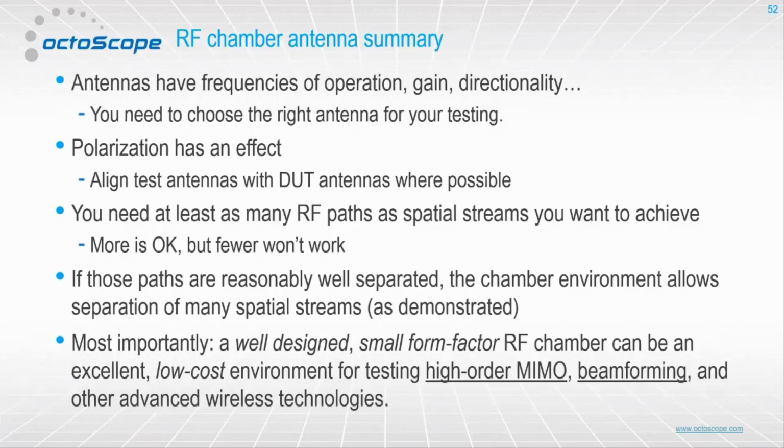So Lee, a little bit along those notes, there's a question here from Nihar asking about antenna polarization and whether it can be used as an independent path. He's asking, is antenna polarization also important for OFDMA gain, and can you get OFDMA benefits by using polarization? Well, that's interesting. So OFDMA doesn't strictly require spatial separation in any way. OFDMA is doing separation in the frequency domain.